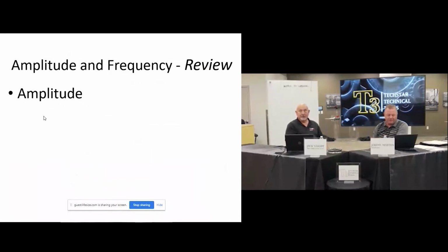So it always pays to do the proper root cause. And Charles mentioned orifice plates. Yeah, they can induce a lot of noise, and that's specific. That's a good point, Charles. So case-mounted sensors, accelerometers, velometers, old seismo probes, things like that, they definitely are more affected by outside vibration sources.